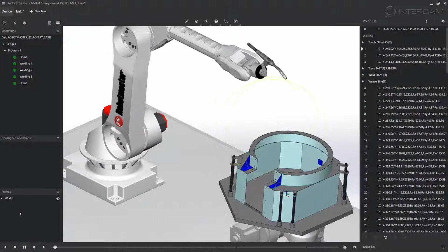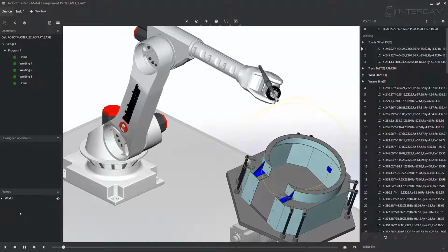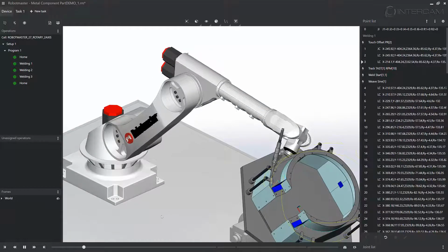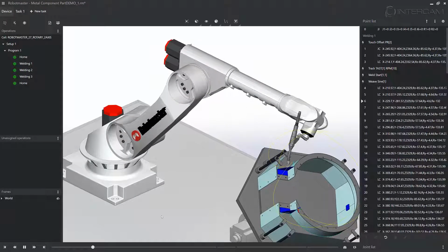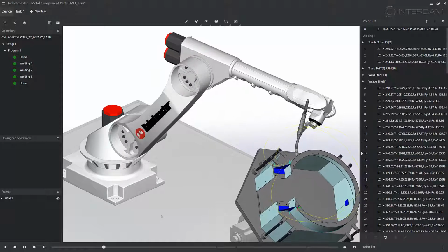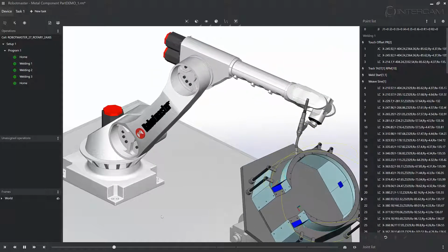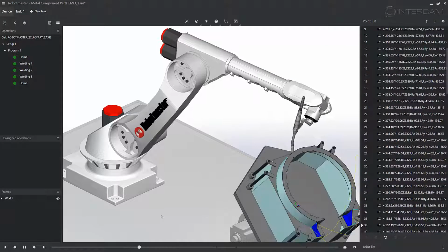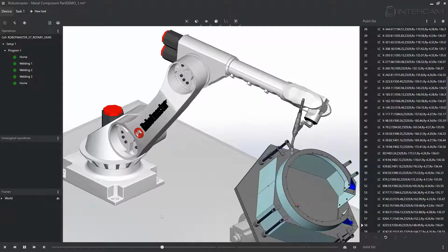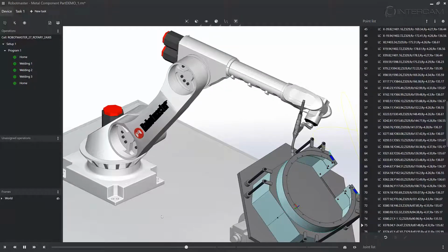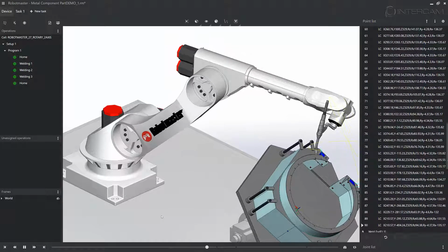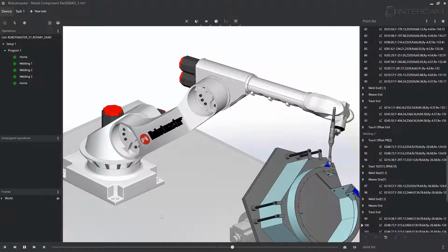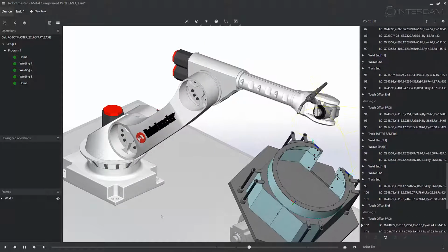Robot Master version 7 has the most technically advanced rail or rotary table management methods in the robot programming market. One function loved by Robot Master welders is the ability to do a combined autosync with a 2-axis rotary table. In this mode, RobotMaster automatically manages the axes of the rotary table, so the welding nozzle is always held at a desired angle with the least possible movement, thereby giving the best quality weld possible.